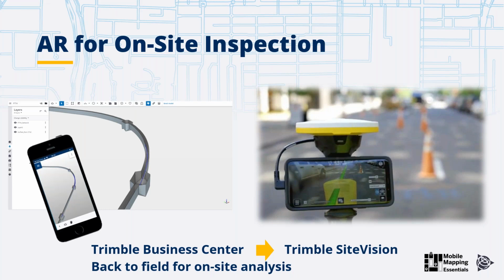Then the application can connect to an internet RTK service provider, for example, a VRS network or a single base based on NTRIP technology. Then you can receive real-time corrections. There is a small IMU inside the system, so you just walk, you get corrections, you walk, you align your system, and then you are good to overlay your model on top of your camera and stream the 3D model on top of your system.